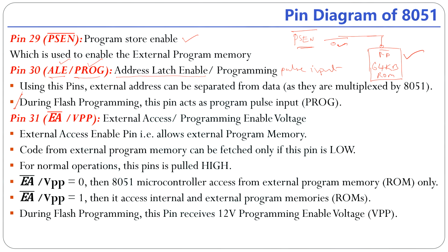So already we know that the 8051 has a time division multiplexed lower order address and data bus, AD0 to AD7. But in extended mode, the 8051 requires separate address A0 to A7 and data D0 to D7 buses.